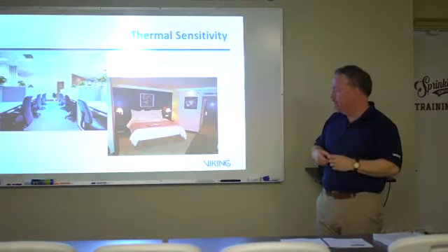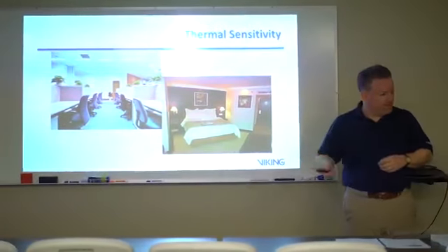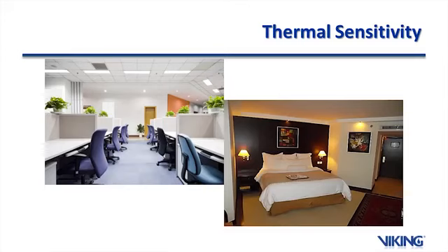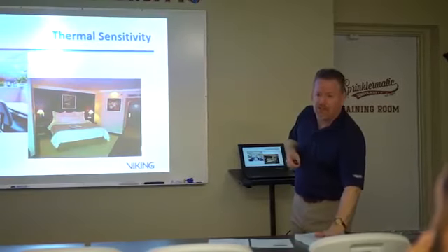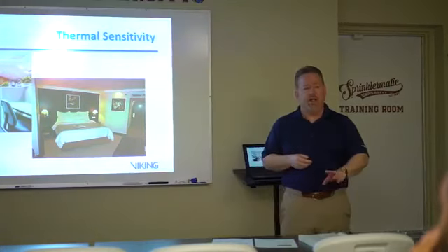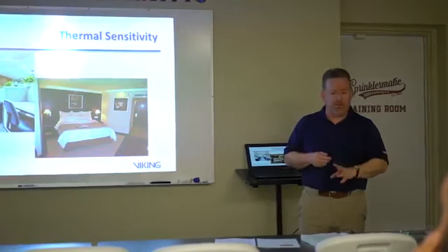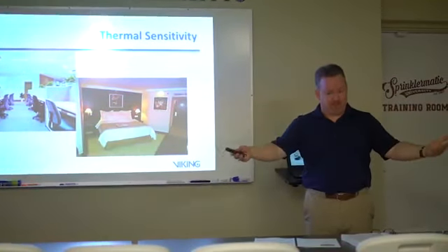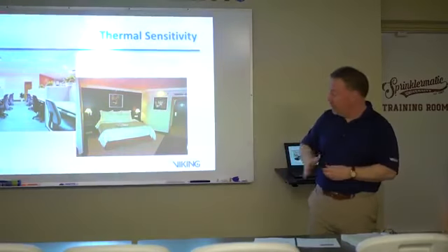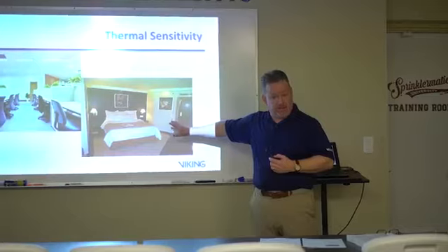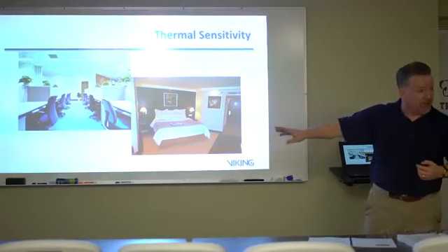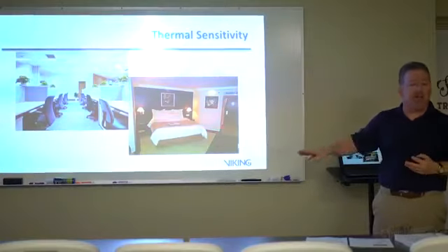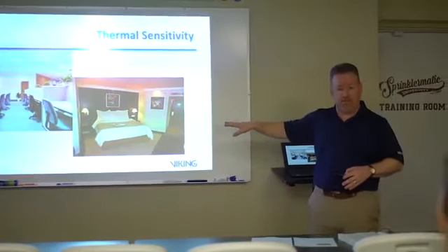Let me show you what we're talking about here. It's important to know this because since 2001, NFPA 13, the book that governs the installation of sprinkler systems, has required listed quick response sprinklers in light hazard occupancies. So if I have an office space considered a light hazard occupancy, or a hotel space considered a light hazard occupancy, it's required that I use quick response sprinklers. I cannot use standard response sprinklers in these spaces.